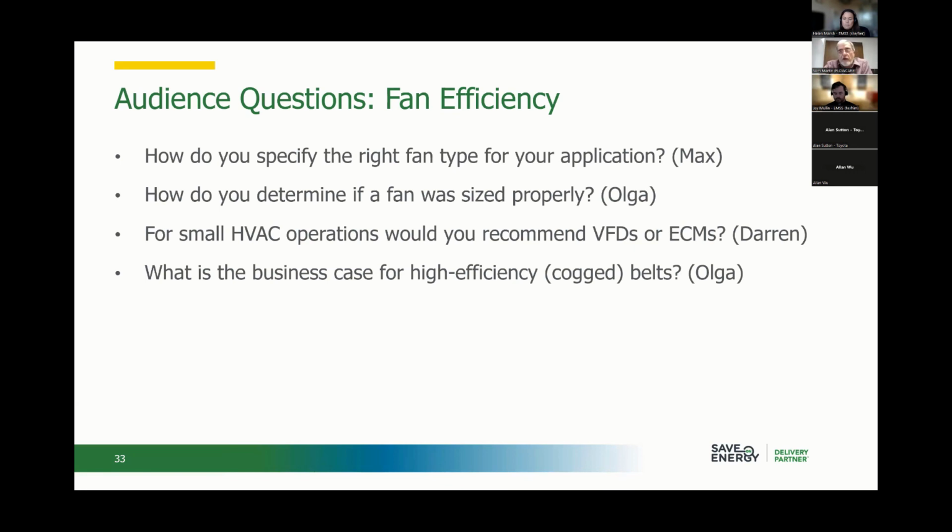And of course, it's a variable because as soon as the belt is installed, the tension on it changes, and the geometry changes a bit with wear and so on. So it's a variable thing, but I think that would generally be the case. Cog belts have less wear, and obviously they're not going to start slipping. As for the business case, essentially you're looking at what my costs are to run it versus what my cost is to install it, what my cost would be after it's installed, and therefore what my payback is on it.